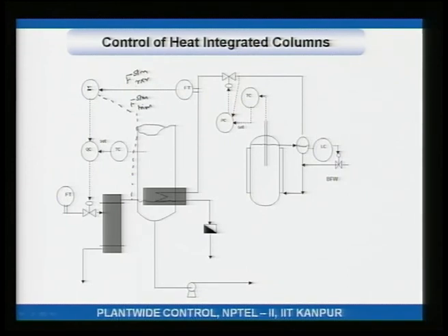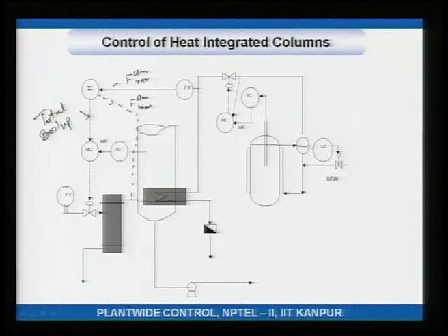So, that is this plus this, this guy plus this guy, this signal is total steam or total boil up, because boil up is nothing but total steam divided by the latent heat of vaporization. So, this total boil up is the signal that goes to this total boil up controller or total Q controller, and the temperature controller is essentially adjusting the set point of the total Q. Instead of adjusting the set point of the trim Q, the temperature controller is now adjusting the set point of the total Q.